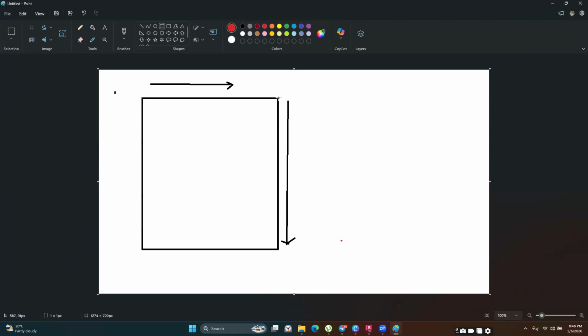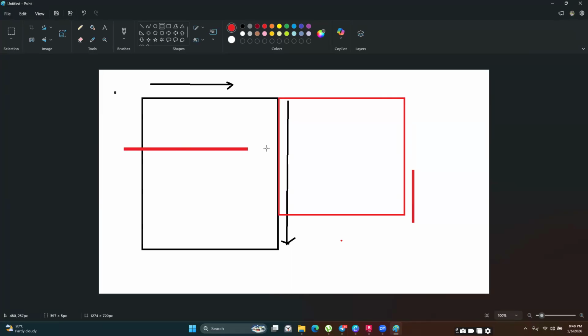If you had this panel here and you modeled it going downwards, you probably have this as your first direction, and then this as your second direction. This would be your X, and this would be your Y. So when you're displaying your results for X, you're going to have moments along this direction for this one, and for this one, they are going to appear in this direction. Because they are going to be maps, they are not going to be cut like this. They may be a bit difficult to understand.